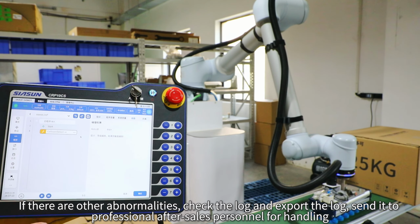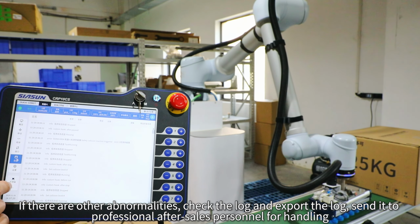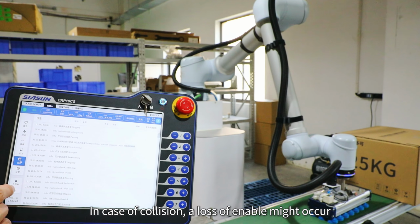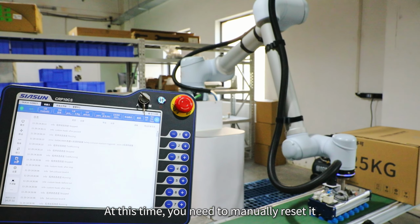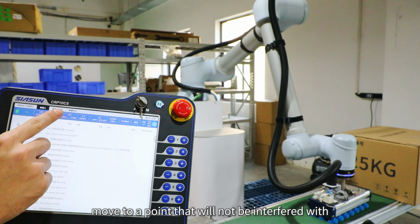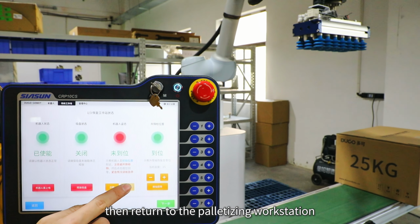If there are other abnormalities, check the log and export the log. Send it to professional after-sales personnel for handling. In case of collision, a loss of enable might occur. At this time, you need to manually reset it. Move to a point that will not be interfered with. Perform robot power on, then return to the palletizing workstation.